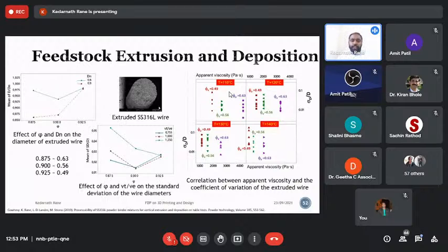The deposition is different. We need to design the rod diameter. We need to design the inter rod spacing. We need to design the layer height. The accuracy of all these parameters is possible through this kind of elemental studies that we have made.